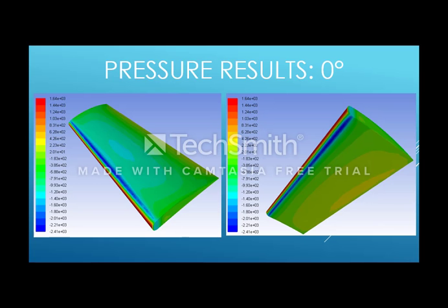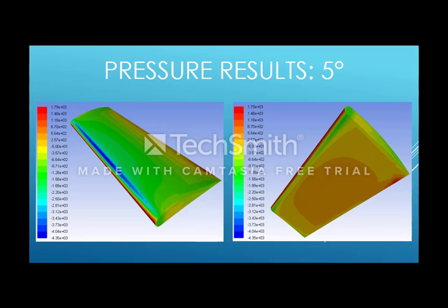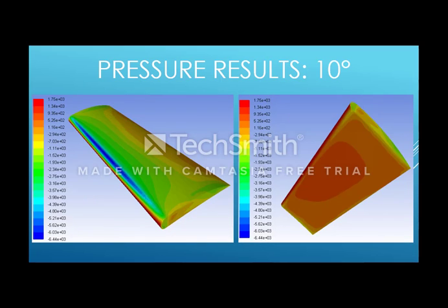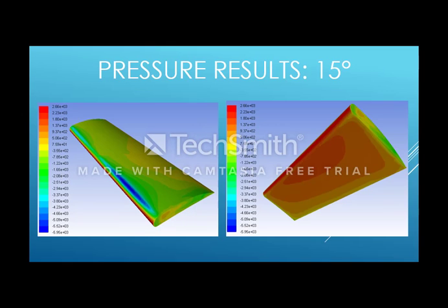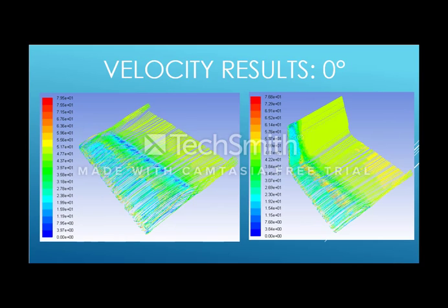The pressure contours generated after a solution was achieved met expectations. There was a lower pressure exerted on the upper surface compared to the pressure exerted on the lower surface. This was the case for all 4 angles of attack. As the angle of attack increased, the pressure also increased. This once again met expectations, as it is known that up to stall, increasing angle of attack increases the lift generated. The interesting results come from a visualization of the velocity path lines.